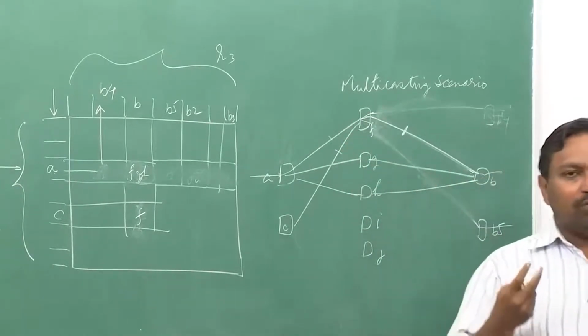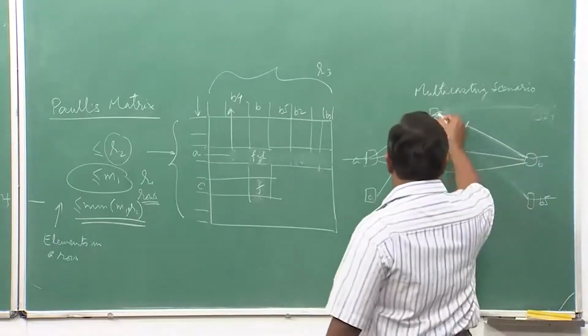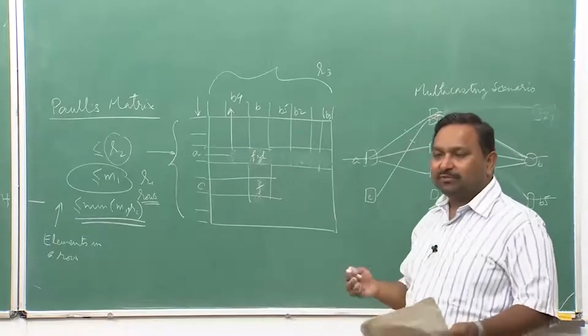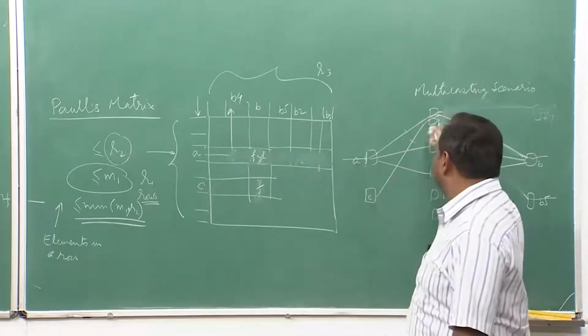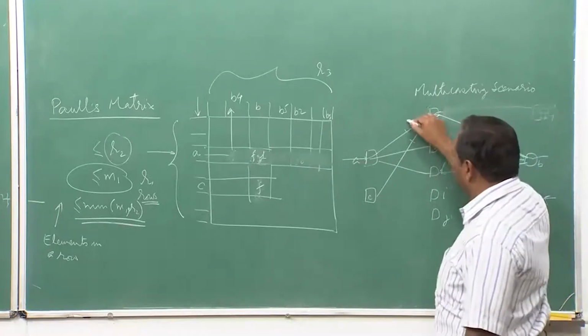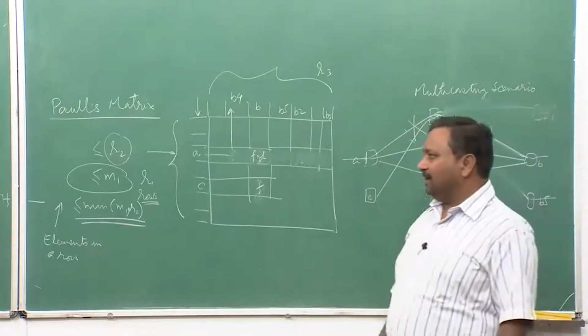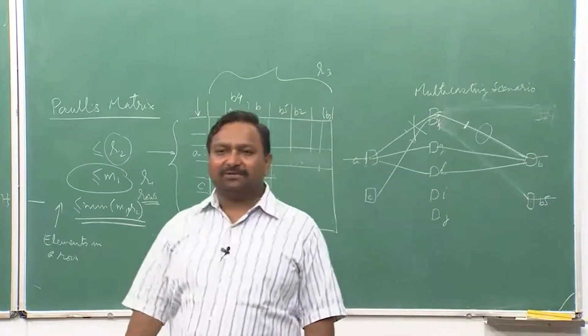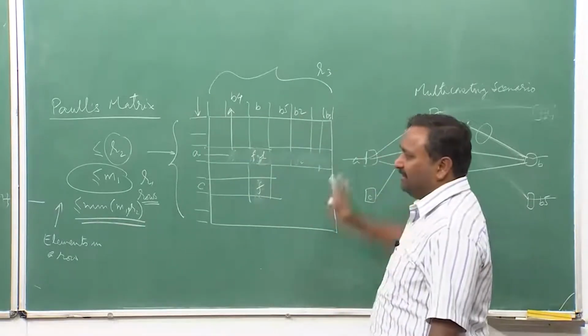It means there are 2 circuits, 2 paths which are coming and they are merging here. It means 2 separate input signals coming from the input side are being put on the same line, they will interfere. So, this is actually illegal, this is not permitted. It is immaterial whether it is multicasting or unicasting, in both cases this is illegal.